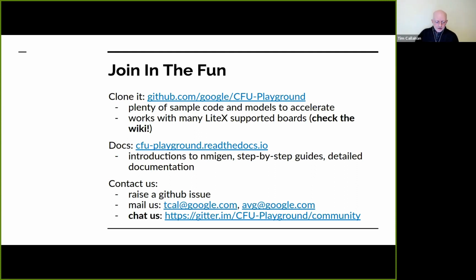Memory bound. Yeah, okay. That's a great question. It can help indirectly with a little more work. For example, let's say you're memory bound by your ML weights. So you could try to come up with a compression scheme so that they are actually smaller in memory, which means that you actually have to move less data from memory, which will help you if you're memory bound. And while normally it might not make sense because you would spend too much time in software doing the decompression once you get it into the CPU, by having a CFU, you can have this decompression occur in a streaming way that doesn't slow you down at all. So indirectly, you can help with memory bound applications. That's my quick off the top of the head answer.